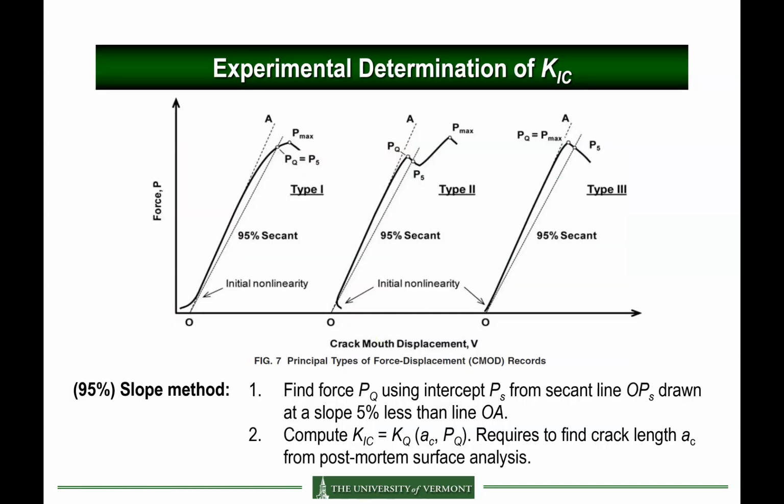So how do you determine the K1C? Focusing on the final stage, we'll be collecting the force and plotting the force versus the crack mouth opening displacement measured from the gauge. And the curve could have different shapes. So the standard gives you how to measure the maximum force. So the technique is as follows.